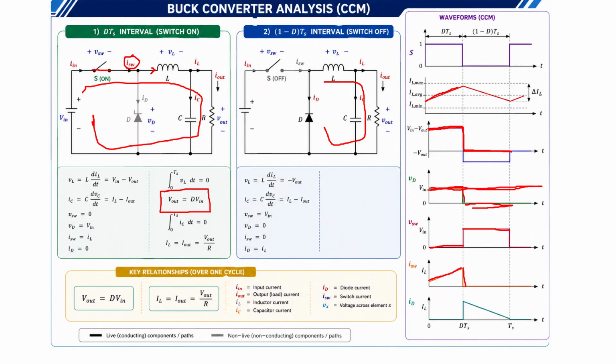The diode is open circuited in the turn on interval, so its current is 0, and the diode is forward biased in the turn off interval, so there is a current flowing through the diode. This is similar to the inductor current, as the inductor starts releasing through the diode. Actually, the current direction is this.